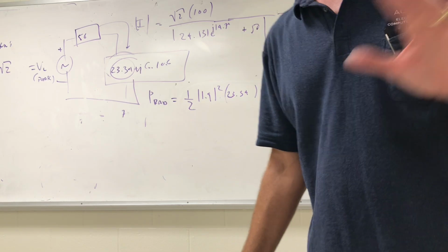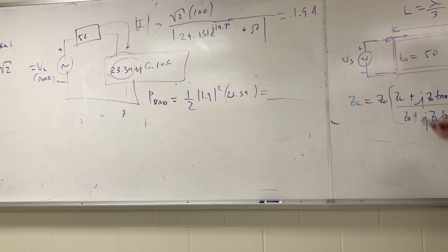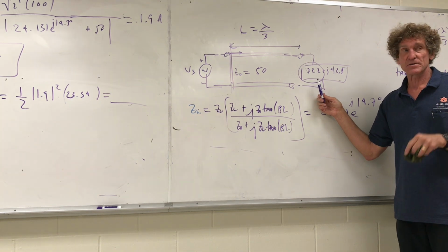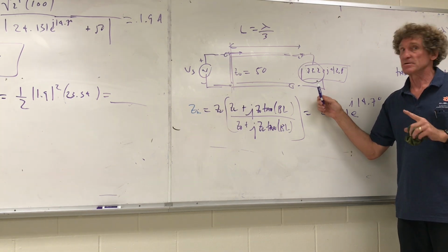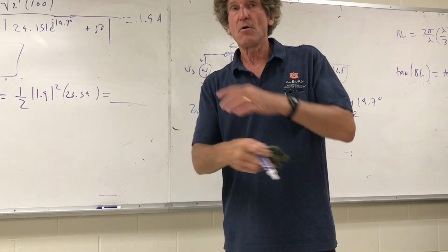But here, the way I've typically done this problem, I'd find the voltage here, V prime, then I'd get V0, then I'd calculate V load, then I'd find the current, then use that times the radiation resistance, 1/2 I squared times the radiation resistance. You don't need to do that. You can just do it right that way. That was the whole point of that problem.